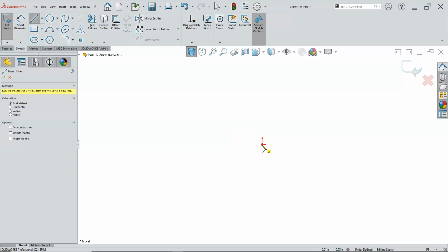So at this stage, we're looking for terminology. And then I wish my little yellow box was a little bit bigger, but that is showing me that I'm coincident to the origin. So as you drag across that and it highlights in yellow, it's going to infer that relation. If it was a white background, then you would be in position, but you wouldn't get an automatic inference.